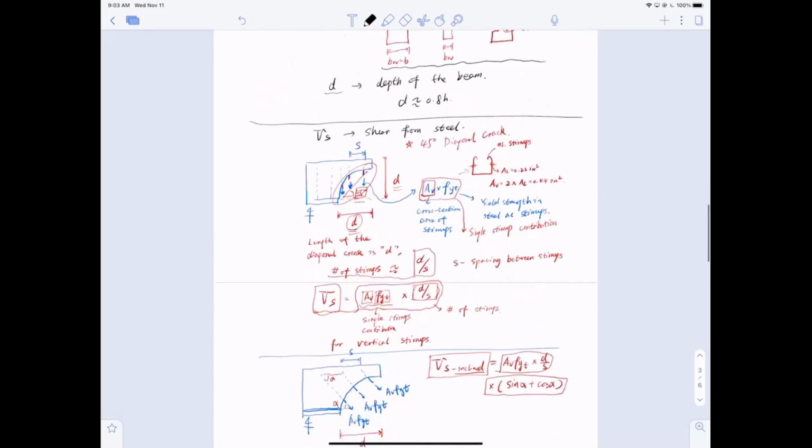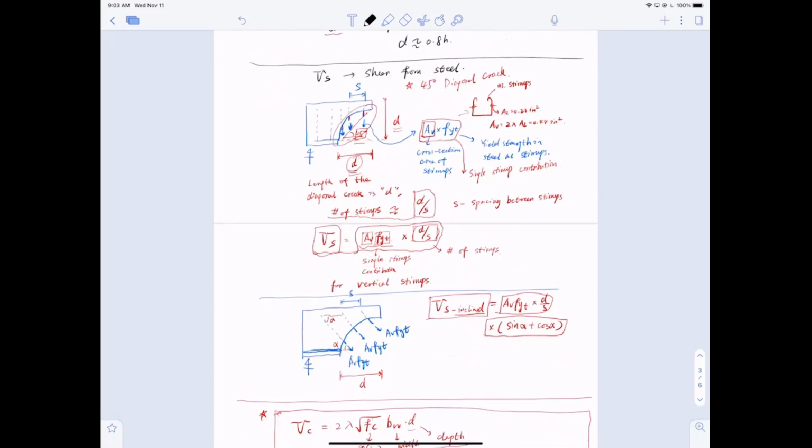And then for the stirrups, now we talk about it, right? The contribution for stirrups is basically the yield strength of steel, fyt, multiplied by Av, which is the cross-section area of the stirrup legs. Now, usually we have two-leg stirrups, okay? So don't get your area wrong. The other thing, for the shear resistance, the stirrups are mainly arranged at a spacing. Okay? And then you have to use the depth divided by spacing to give you the effective resistance from the stirrups,